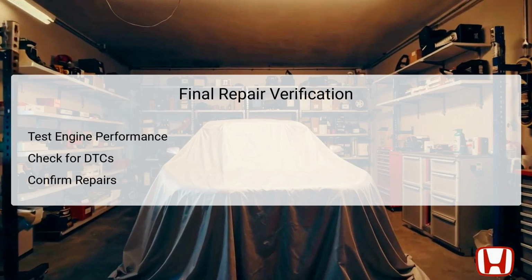After troubleshooting and potentially replacing faulty components associated with DTCs P030A, P030D, P031A, or P031D, it is crucial to perform a final repair verification. Start by testing the engine performance to ensure that it is running smoothly. Engine performance should be stable, and acceleration should respond appropriately without any misfires or stalling.